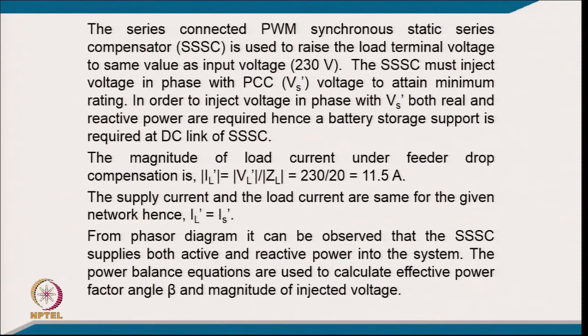Then the series connected PWM synchronous static compensator is used to raise the load terminal voltage to the same as the input voltage of 230 volt, and the SSC must inject the voltage in phase with the PCC voltage to attain the minimum rating. In order to inject voltage in phase with the Vs dash, both real and reactive power are required. Hence, battery storage support is required at the DC link of the SSC.